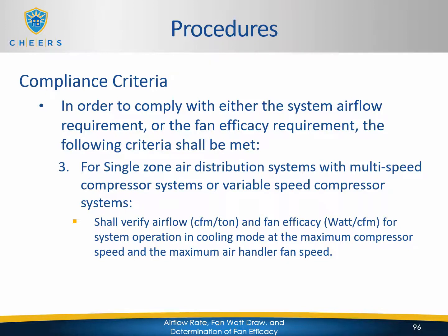Also keep in mind that depending on the type of system you're working on, you're going to be testing it in different ways. For single zone air distribution systems with multi-speed compressor systems or variable speed compressor systems, but regardless single zone, you shall verify the airflow and the fan efficacy for system operation in cooling mode at the maximum compressor speed and the maximum air handler fan speed. There are different ways you test single zone versus multiple zone systems, so we're going to be covering multiple zones next.